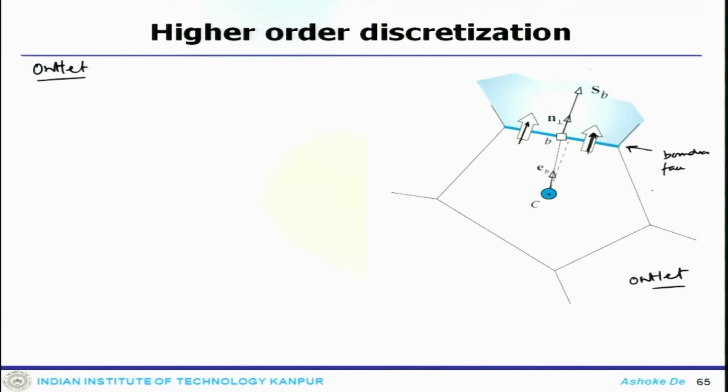So, in fact, the upwind and the second order upwind scheme, for example, do not require any information at the outlet, since all its value can be expressed as a function of the value at upstream. If you look at pure first order upwind and second order upwind, they use all the information from the points which are sitting ahead of it.